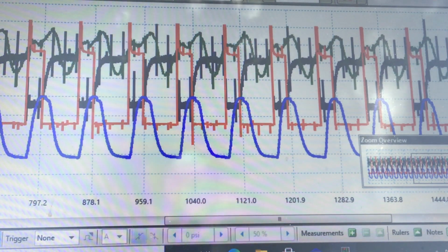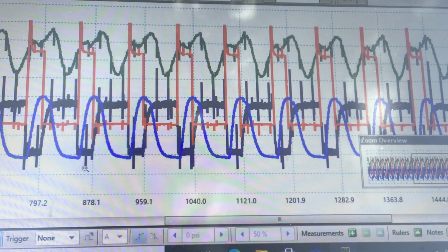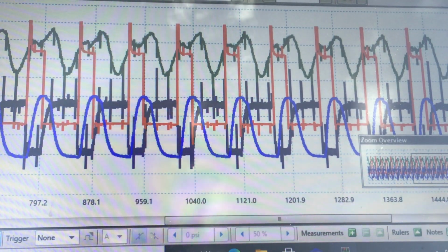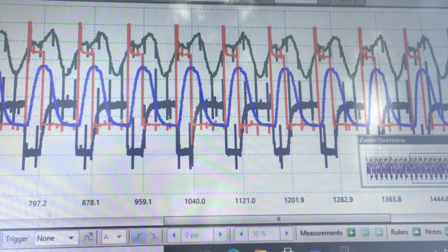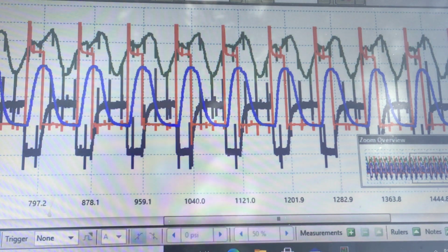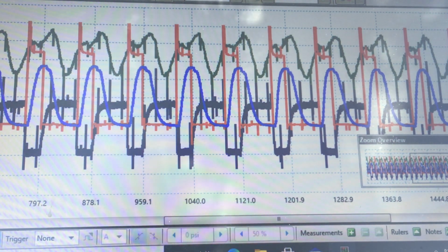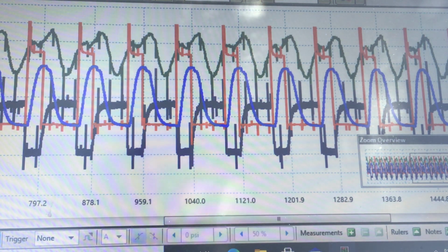That's the ability of the scope to have a lot of vertical zoom. We can just see how our blue, our transducer, and our fuel tank pressure sensor are kind of lined up. That's a good validation that our fuel tank pressure sensor is accurate. It's working, and it's in its right zone. It's in its right level. If it were skewed, that could definitely cause a problem, cause evap codes, things like that. So right there, we see all the action-reaction on our canister purge solenoid.